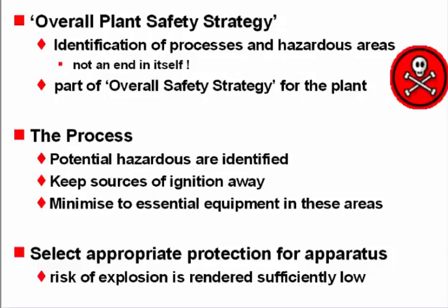So once we've got the process sorted, that will allow us to identify where the potential hazards are. We know if we've got a process vessel where we're storing the, shall we say, the petrochemical, then obviously inside that tank itself is highly likely to have the hazard there all the time. In the pipes that are feeding it, then they are likely to be there all the time as well.